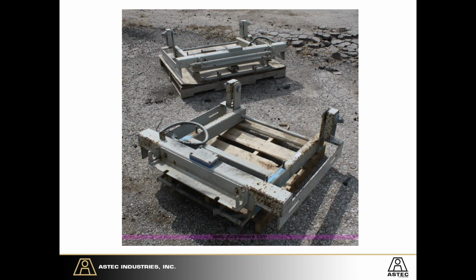To go over the evolution of weighbridges, these are some old weighbridges here, Ramsey weighbridges. They are a very well-known weighbridge, done very, very good. One of the things that a lot of people noticed on them, they did have some mechanical inadequacies, and that was the rubber bushings in those. As those bushings wore, they would cause some inconsistent mixes.